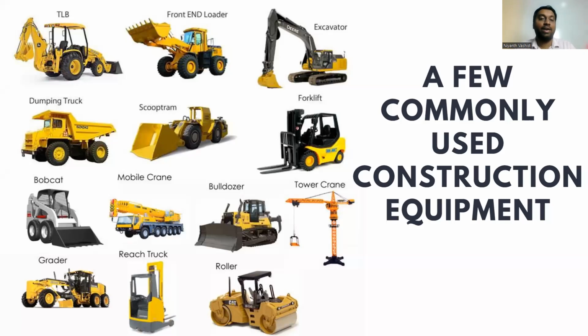The second one is a front end loader. This is something that we'll be seeing especially in the mining sector and wherever there is a huge site and transportation is required, because a front end loader is a very fast vehicle compared to the backhoe loader or the TLB. So wherever there is space, wherever speed is required in transportation of material, front end loader is something that we look at.